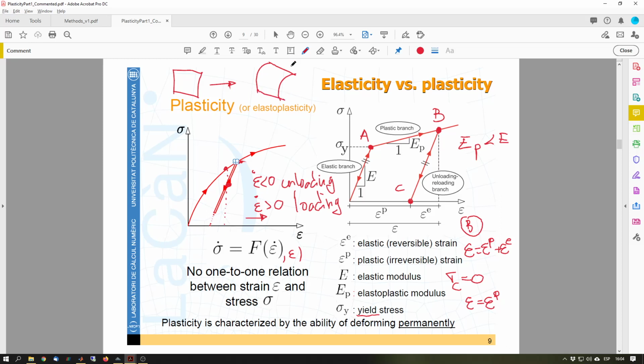That's what you want to put in the chassis or any shell that you want to build your car shape from. So you create some plastic strains. Initially the plastic strain would be equal to 0. Then I apply some stresses and create some plastic strains, which may be larger than 0. Anything may happen, but I have created some plastic strains.